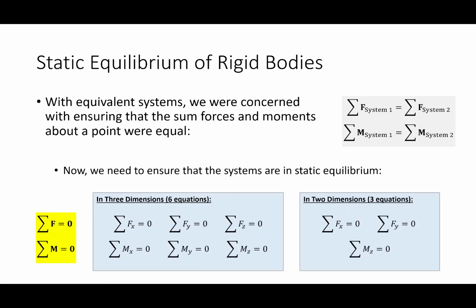What about a system of vectors in 2D? Well, if we were talking about forces in 2D, we would not consider that, right? We wouldn't consider that because we wouldn't have any forces in the 3rd dimension. What about the moments? Which moment term is the only one that exists in 2D? If you have forces across the x-axis and the y-axis, then your moments spin about the z-axis, right? So these terms go away in 2D, right? So 2-dimensional problems are not 6x6. 2-dimensional problems are 3x3, okay?